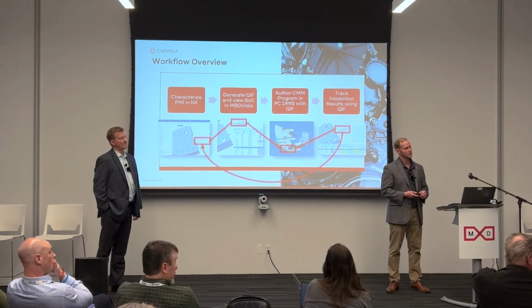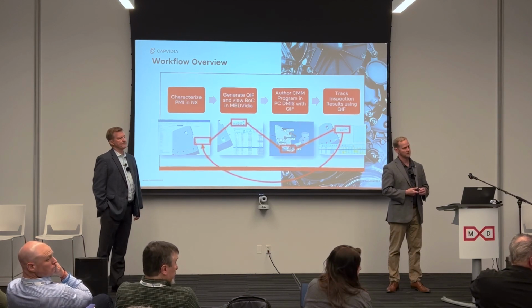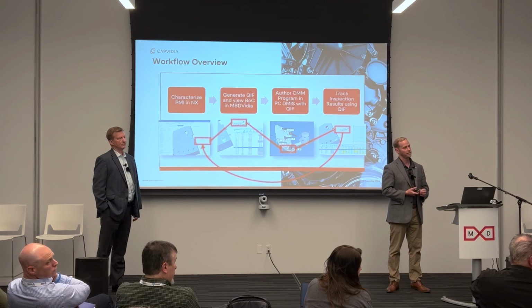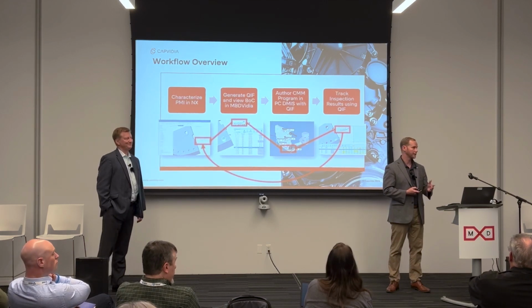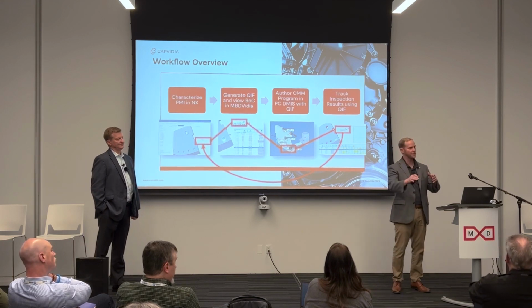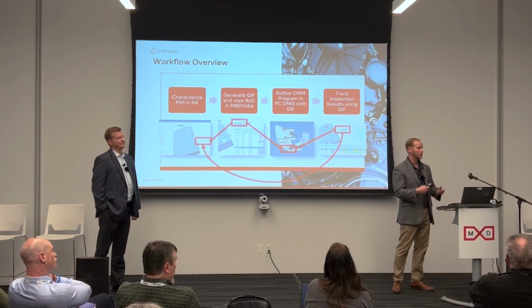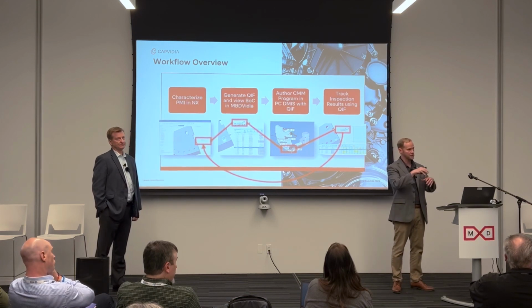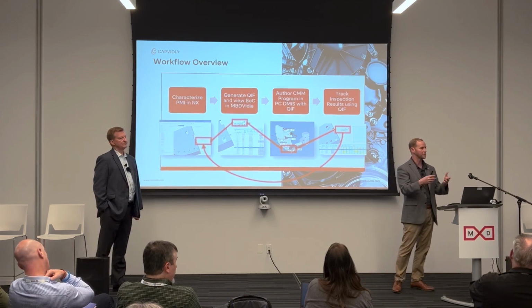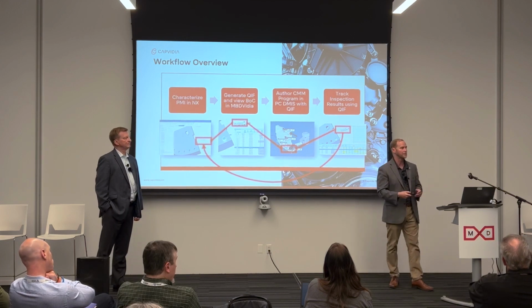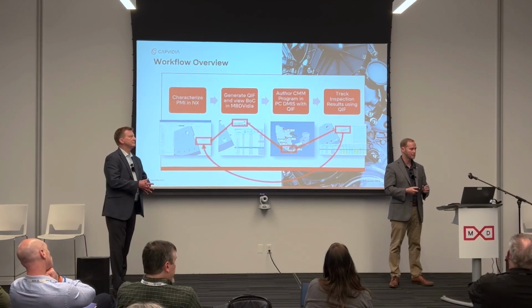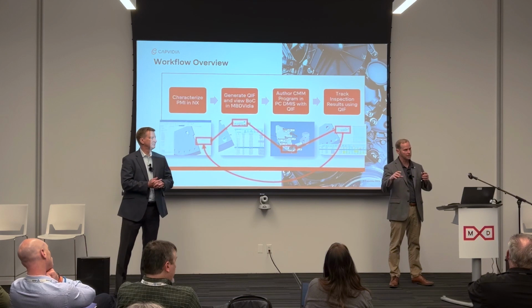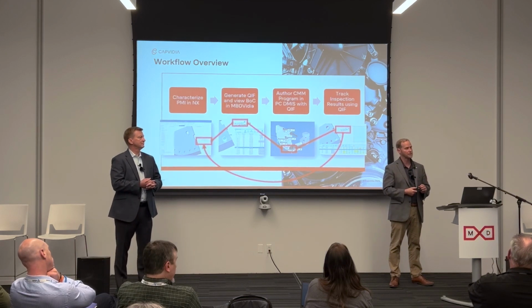We already have built in the other shape feature, which is nothing but a collection of faces. That would be the fallback if it was some type of a free-form surface or something. But it's quite easy to say this surface or these couple surfaces, we look at them, they represent a cylinder shape, so it's a cylinder feature. And so that type of feature creation is pretty straightforward with the associativity of the PMI to the surfaces.